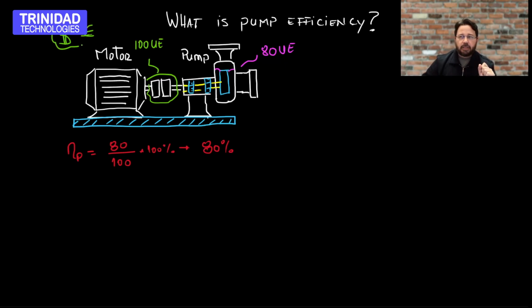You are paying money to push water or to convey water to certain places, and part of that money is not fully used to do the job. So the lower the efficiency of your pump, the more money in excess you have to pay to do the job. Meaning efficiency is highly tied to finances. Let's write it down here: efficiency is fully related to money.